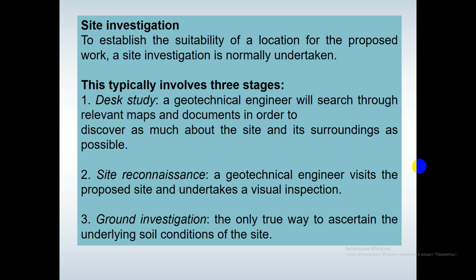From the information gained from the site investigation, the following inter alia should be established: adequate and economic design to be prepared, the best method of construction, suitable use or disposal of in situ materials, the changes that may arise in the ground and environmental conditions as a result of work.